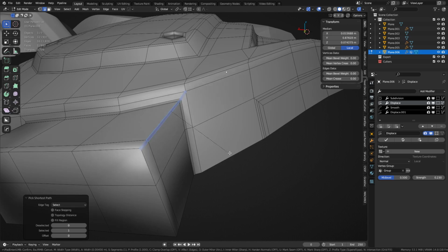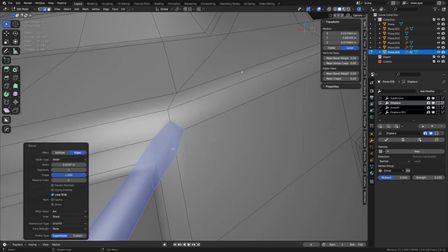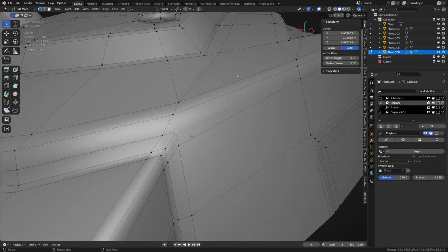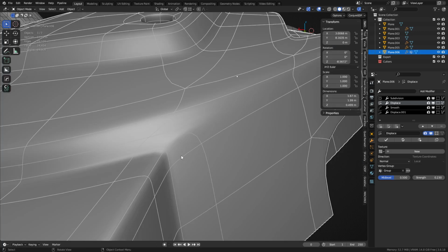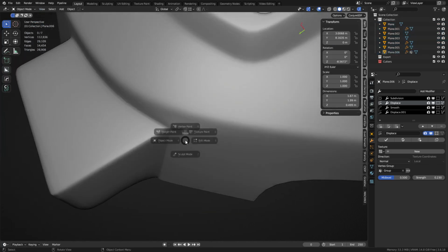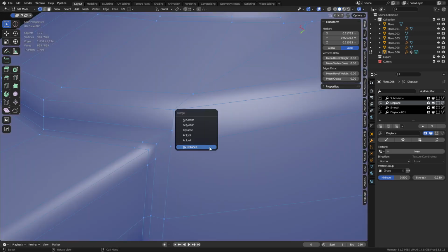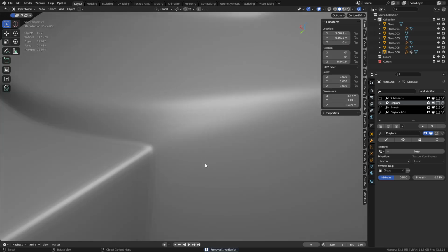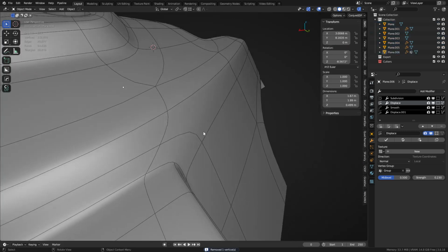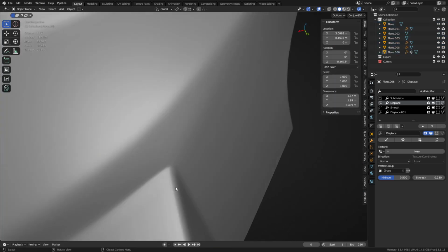In our case here, I'm going to bevel. This is another technique. And then you can dissolve, right? And this would normally run to that next vertex that's up here, but this is a very long stretch. Just leave it as an end-on a lot of times. It might create a little distortion here. That's possible. You can try different techniques of working this out, basically. There's different things you can try to do, like using triangles or n-gons or whatever. So like doubled up n-gons, who knew, right?